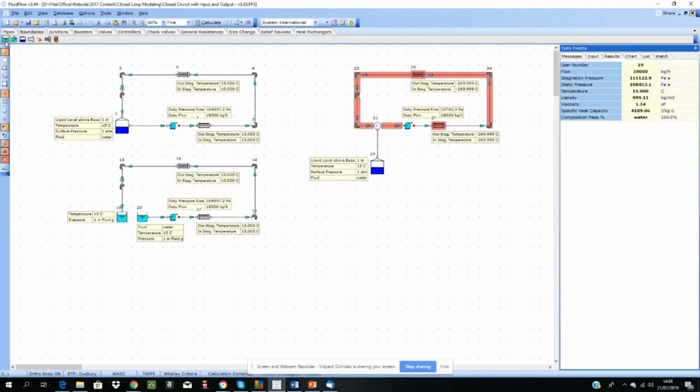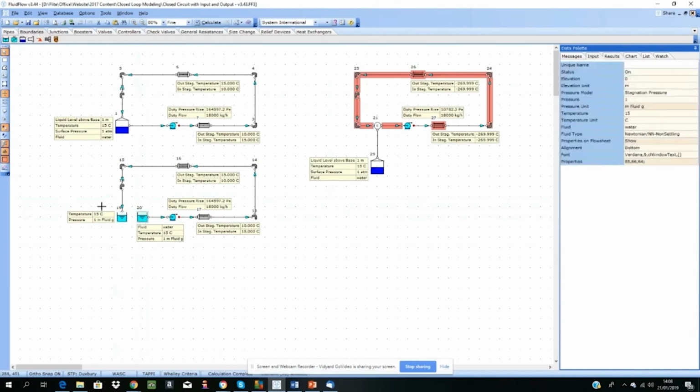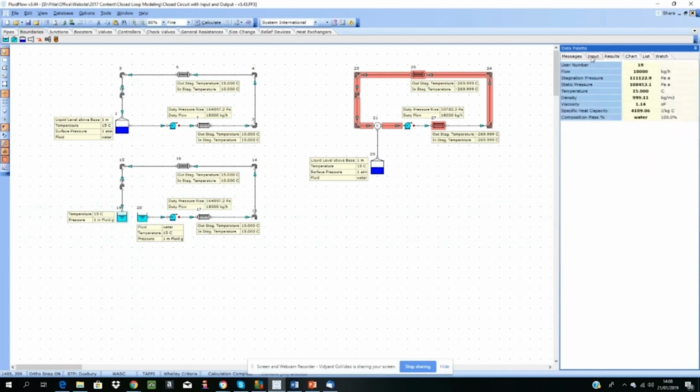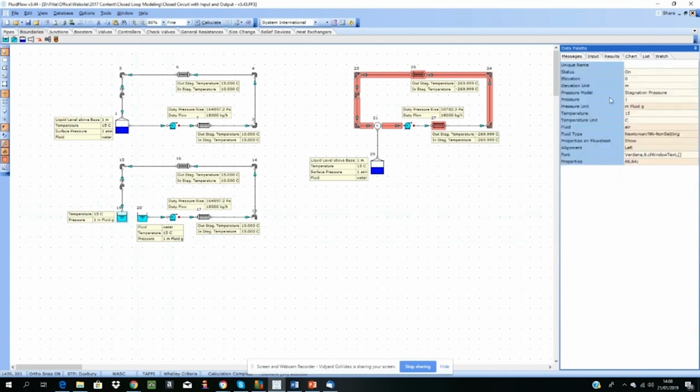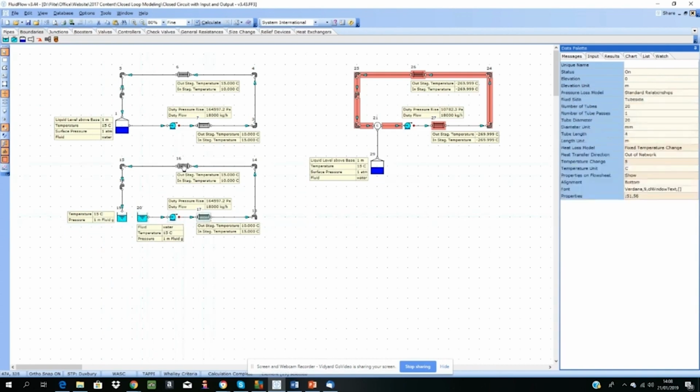Remember, the boundaries known are assigned pressure. That just means in that case its known information is the input. Whereas in this position, this is actually the outlet. So the assigned value you want to look at is the results. But the design condition, pressure-wise, is the same nonetheless in both cases. We've got our pump with 5 kilograms per second, our heat exchanger with 5 degrees Celsius temperature change, and the results are identical essentially in both cases.